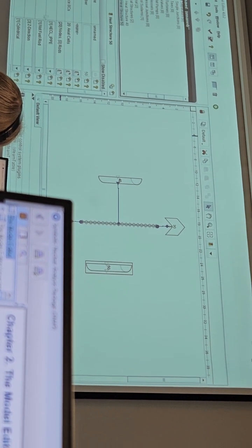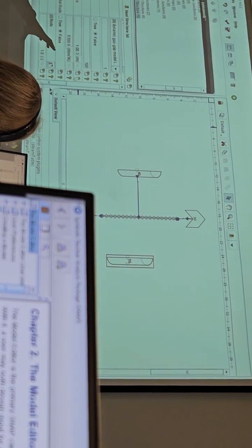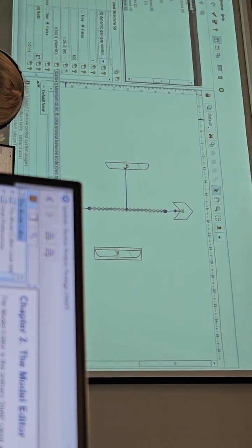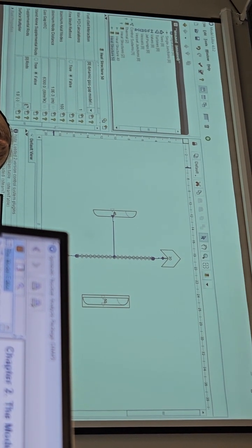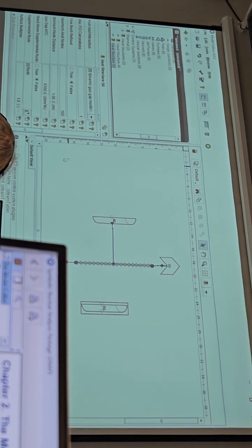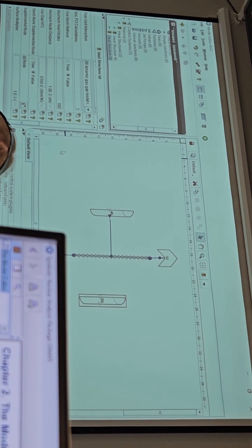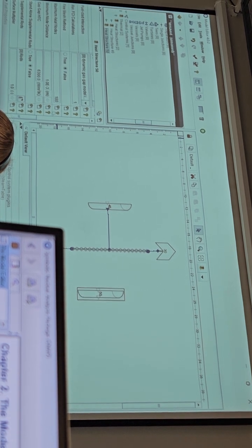Here it is represented as 1, and here's a surface multiplier. You can build 1 and multiply it by 70, 100, 1000, depending on how many heat structures you want. For reactor core modeling, you can multiply it by 12,000 to represent each fuel rod inside the reactor core.